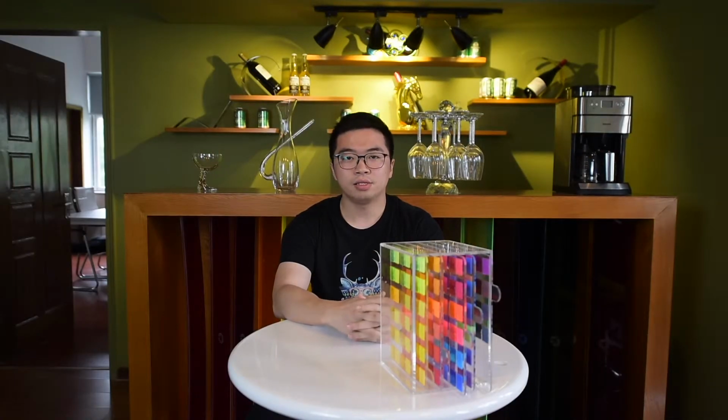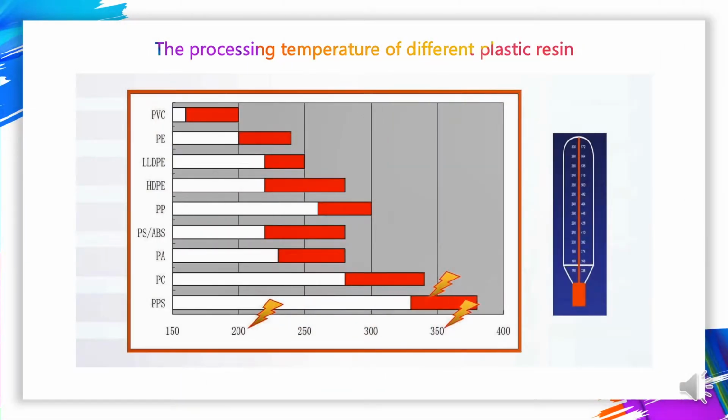In the early days of the plastic industry, processing temperatures above 200 degrees were rare, but now 300 degrees or higher is normal. The processing temperatures are different for each kind of plastic resin. Honestly, it is meaningless to require all colorants to reach 300 degree heat resistance.